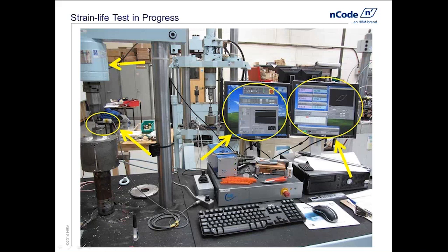That is measuring the load that's transferred to our specimen from the test rig. Our specimen is down here, gripped between these two grips, and attached to it is an extensometer. Basically, it is an instrument that's clamped onto the specimen at the gauge length, measuring the strains that go on in that specimen as I load it.